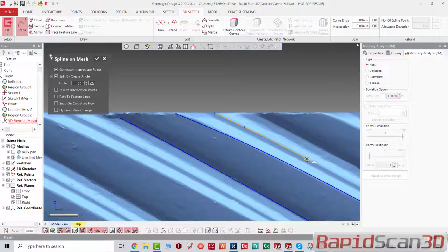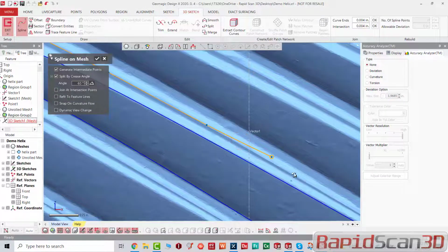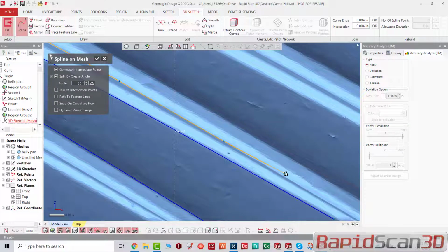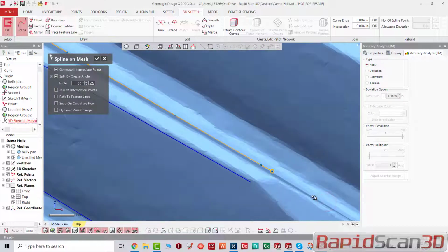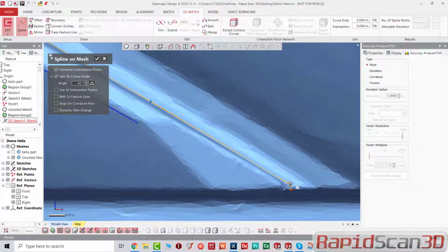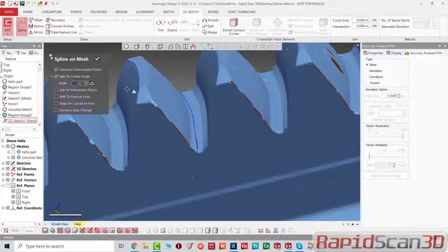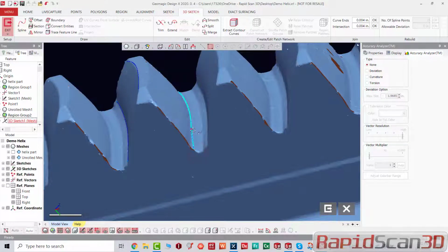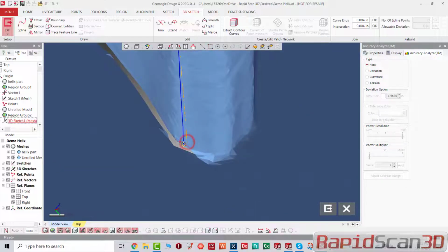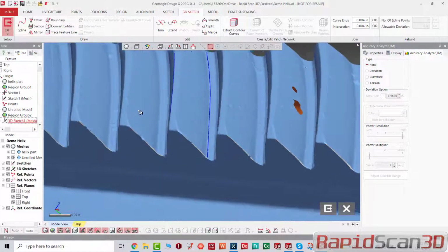Once I start creating this curve pattern, I can project that onto my actual CAD model. Finish with that. The last area, I can cut that later, that flat surface. And you can see I can adjust my spline on the curve. It's a great, powerful tool.